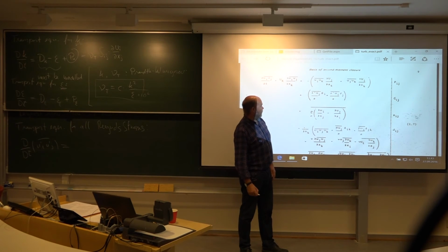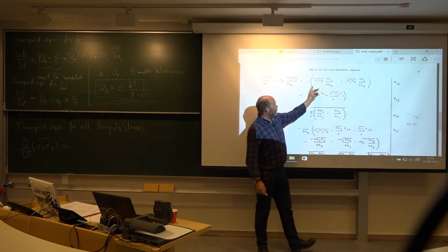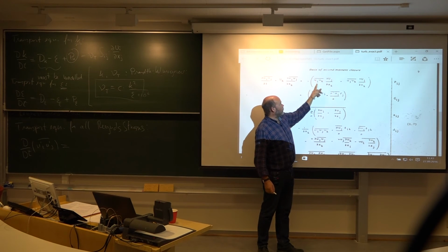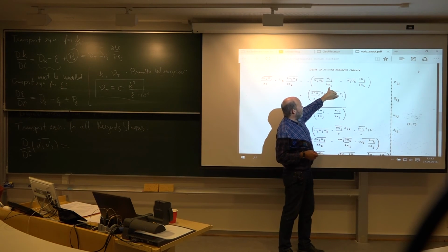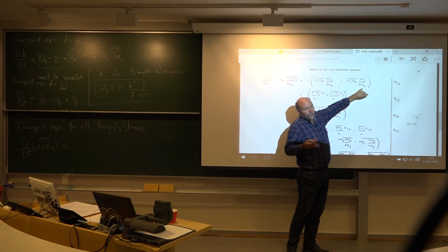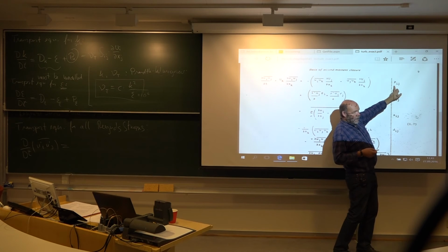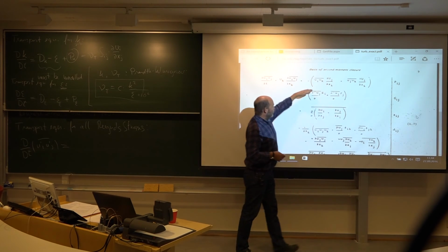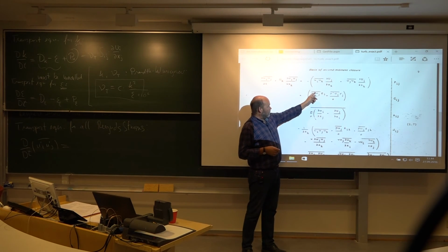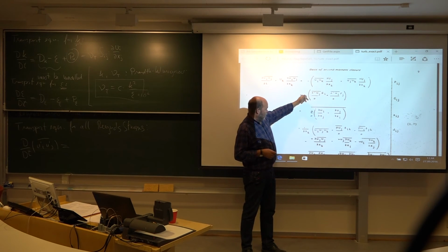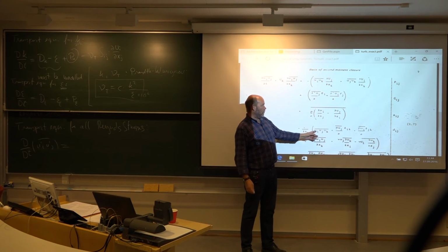No way you can deal with this, except the first one. This one is analytical. Remember, u fluct, they are already unknown. These are the Reynolds stresses. And here just multiplied with the average velocity gradients. Again, already unknown. So the production term, this we have exactly, an analytical expression. The rest you can forget. No way you can handle this. Pressure fluctuation multiplied with the velocity. Triple correlations, forget it. This is very, very hard to find correct.